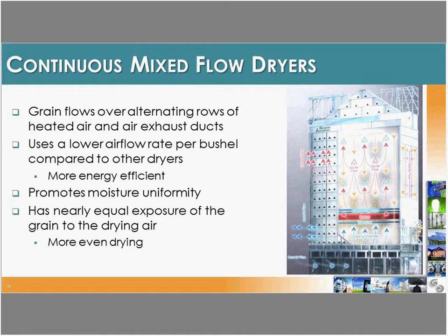This is where the grain flow provides mixing of the grain and an alternate exposure to the hot drying air and the air that has been slightly cooled by previous contact with the grain. So the grain flows over these alternate rows of heated air and air exhaust ducts. If you look at the picture, you'll see the grain flow coming down where you'll have the heated ducts and the cooling ducts.